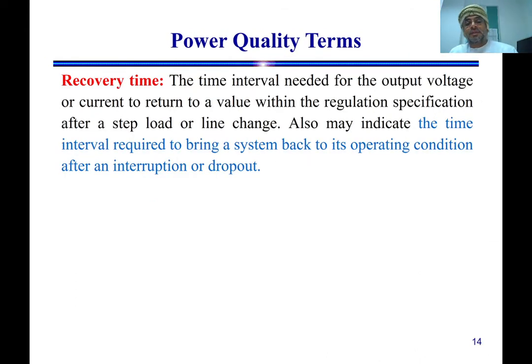Okay, what we mean by the recovery time. Recovery time is the time interval needed for the output voltage or current to return to a value within the regulation specification after a step load or line change. Okay, so it is the time interval needed by the voltage to return to the initial value.